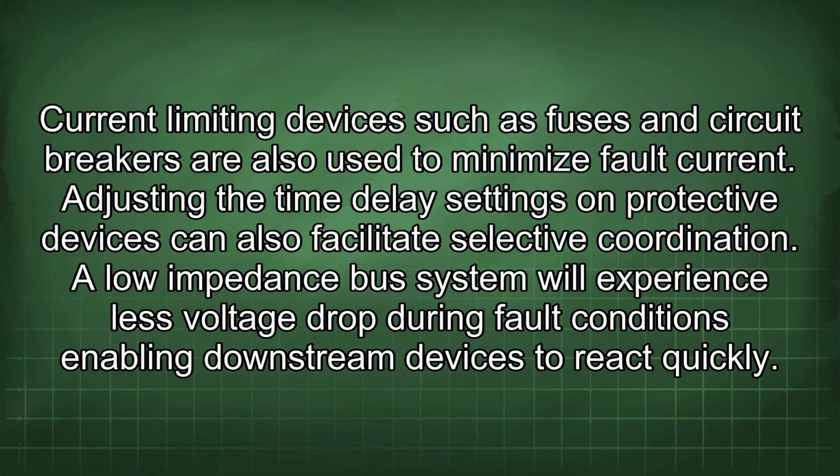Adjusting the time delay settings on protective devices can also facilitate selective coordination. A low-impedance bus system will experience less voltage drop during fault conditions, enabling downstream devices to react quickly.